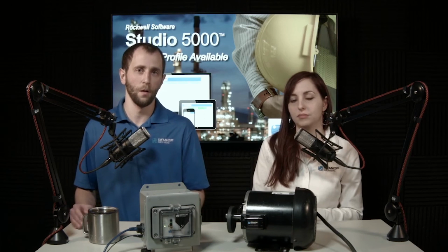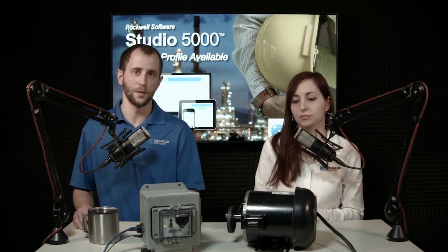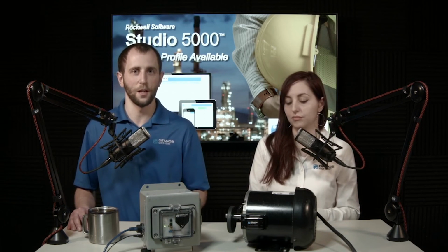Yeah, there are a few options. Most of the other ones involve epoxy, or you could do a direct stud mount as well, using a 1/4-20 stud. The fin mount would be just in the fins. You'd have a mount that we put in epoxy, and then you can mount our VBT to that. So there are a few different options. If it's not magnetic, we're going to have to do a different solution. But a lot of our customers, at least for starter kit systems, beta systems, typically do the magnetic option, and on the larger deployments, we can make an adjustment on what type of mounting makes sense.